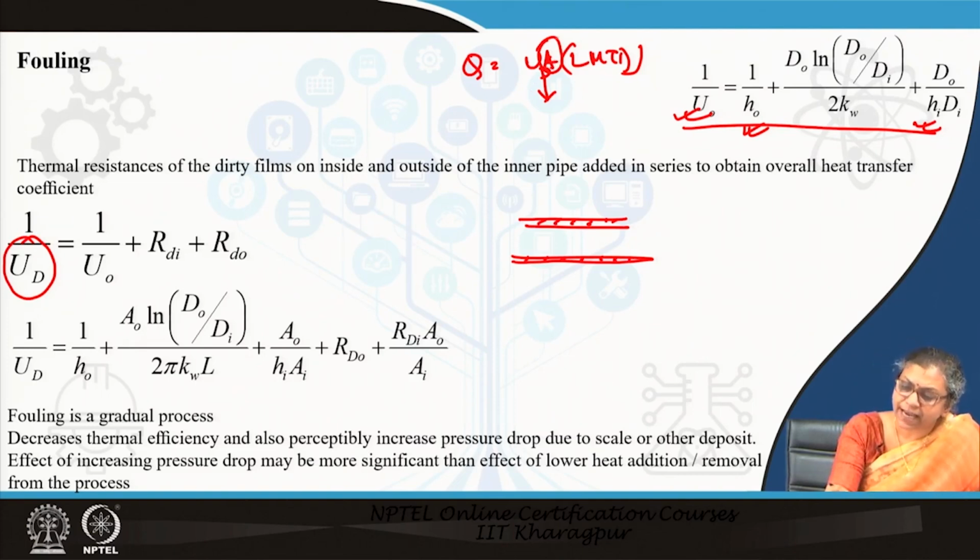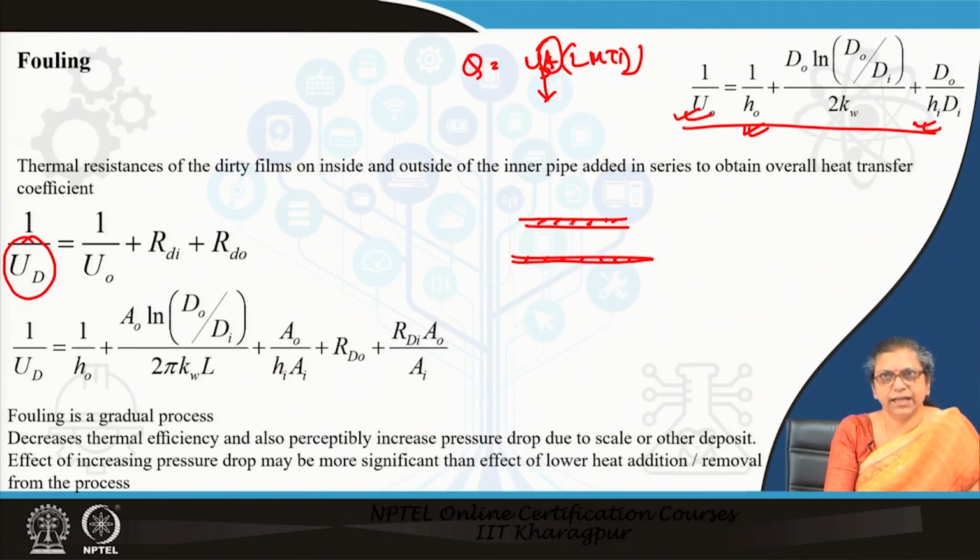This additional A that you provide will ensure that even with sufficient fouling, even with aging, the heat exchanger will be able to provide the heat exchange that you want. The hot fluid will be cooled to the extent that you want, or the cooled fluid will be heated to the extent that you want.